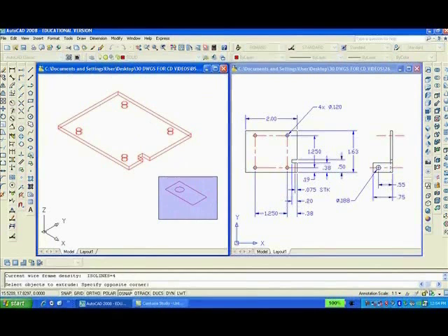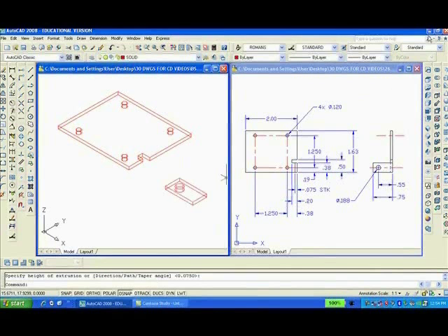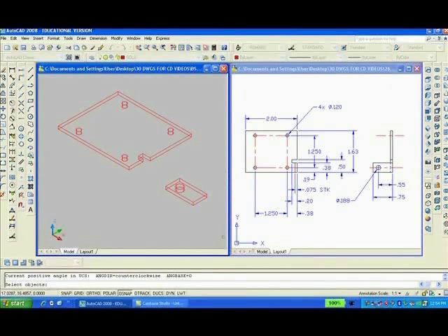EXT enter. I'll extrude the hole as well as the part, enter. 0.075, I'll accept that, enter. So now I want to subtract from the small block, enter, the small cylindrical hole, enter. Now I think we want to use 3D rotate.